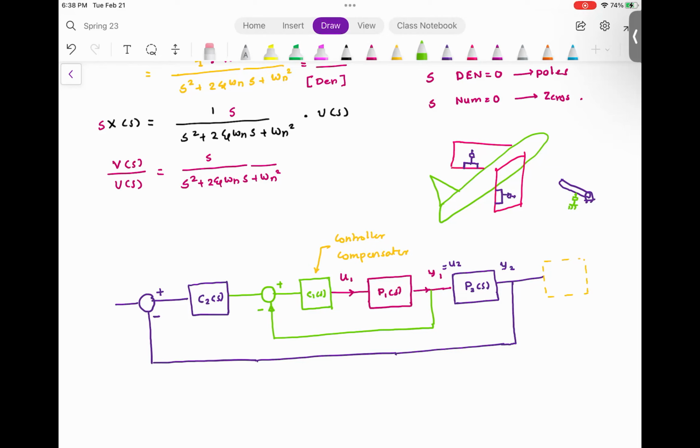orientation of the aileron. The practical application here is that the hydraulic actuator has a finite length. A hydraulic actuator cannot extend infinitely, which means it is going to saturate at some control input. Now, what does that saturation mean? Typically, you are going to use some type of motor control or control logic to excite that hydraulic actuator.